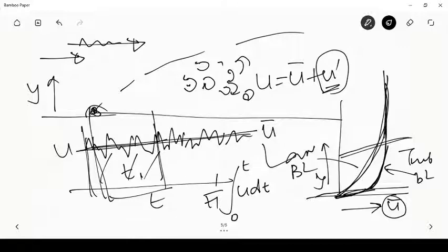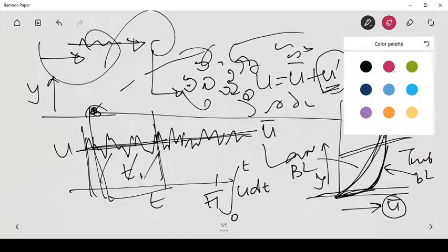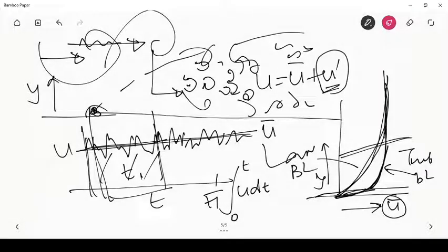So you will have small eddies, you will have the large eddies that come from the main flow, and near the wall, because of breakup of those eddies, they become smaller eddies in this region. So if I introduce, for example, a dye from here, the dye naturally cannot remain smooth, but it will get carried by this a little bit, and then this a little bit, and this a little bit, and therefore it actually diffuses very quickly and disappears in a very short distance. And that is the nature of turbulent flow that you normally have. So this is what we understand by turbulent flow.